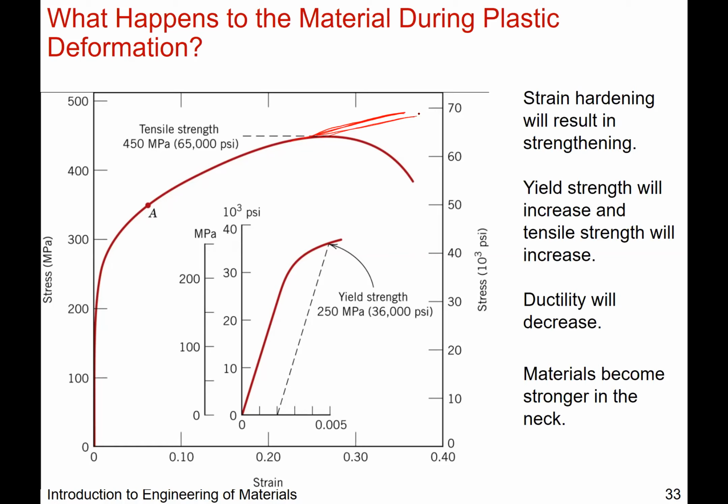So the traditional stress strain curves that you see in databases look more like this one, where it looks like your stress is going down to the point of fracture because you're normalizing by the initial cross-sectional area and the initial length versus the instantaneous length. Okay, so that's the difference between engineering stress versus the true stress of a material.